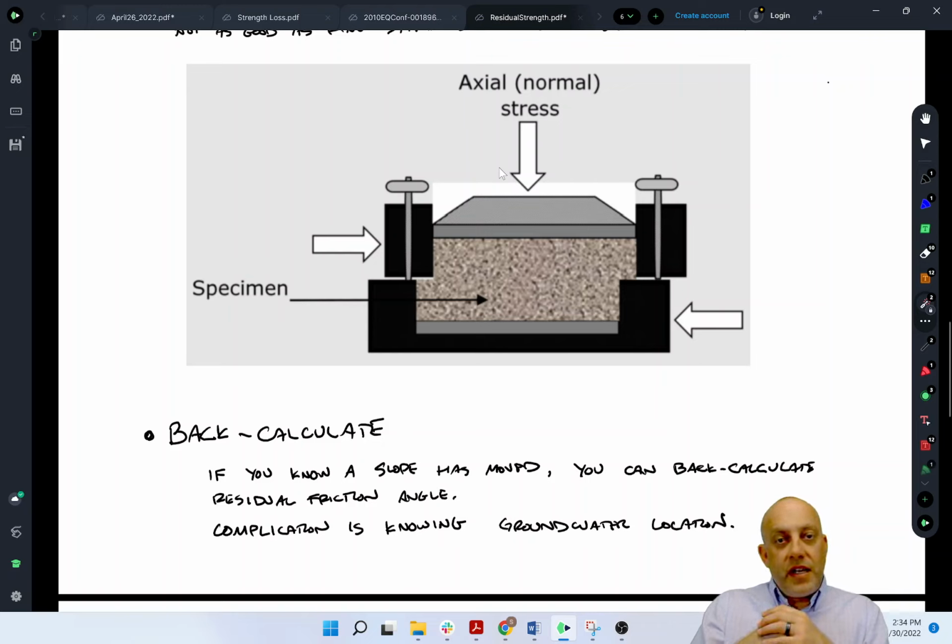The other good thing is that you're going to be using some sort of analysis tool, and you want to make sure your analysis tool is calibrated to reality. And so it could be that the number you have to put in your analysis is not actually the real friction angle because there's counterbalancing errors, but at least if you can get a friction angle close to 1, you have some faith that your analysis is reasonable, and you can then evaluate a mitigation strategy using that same model.